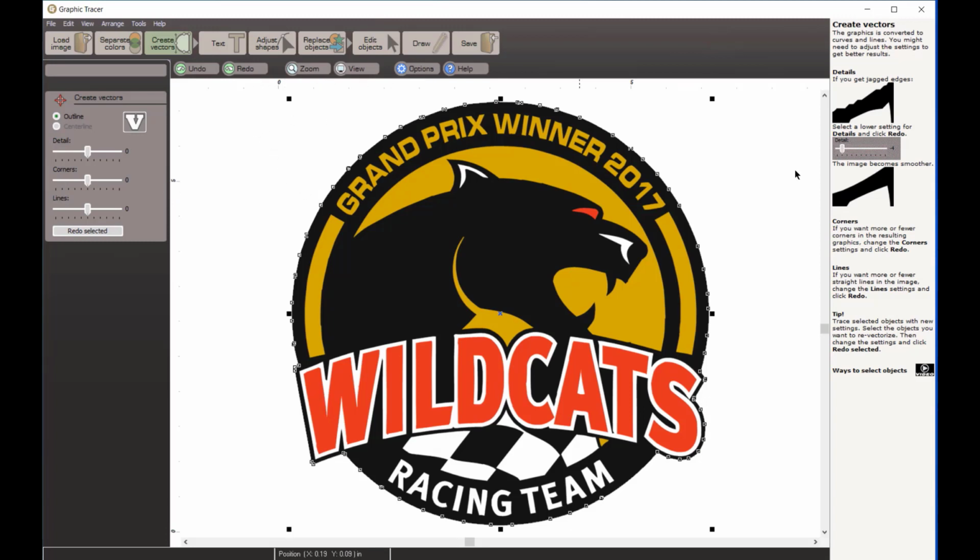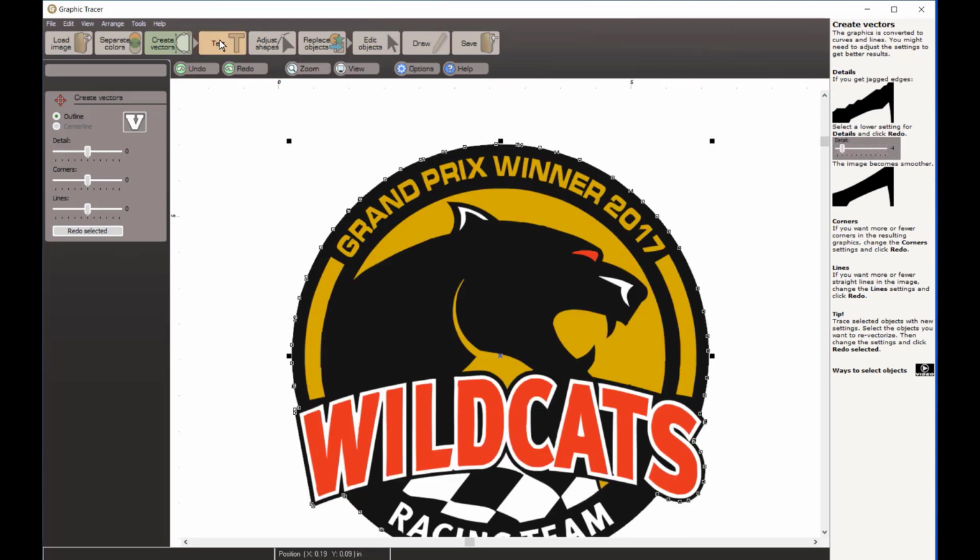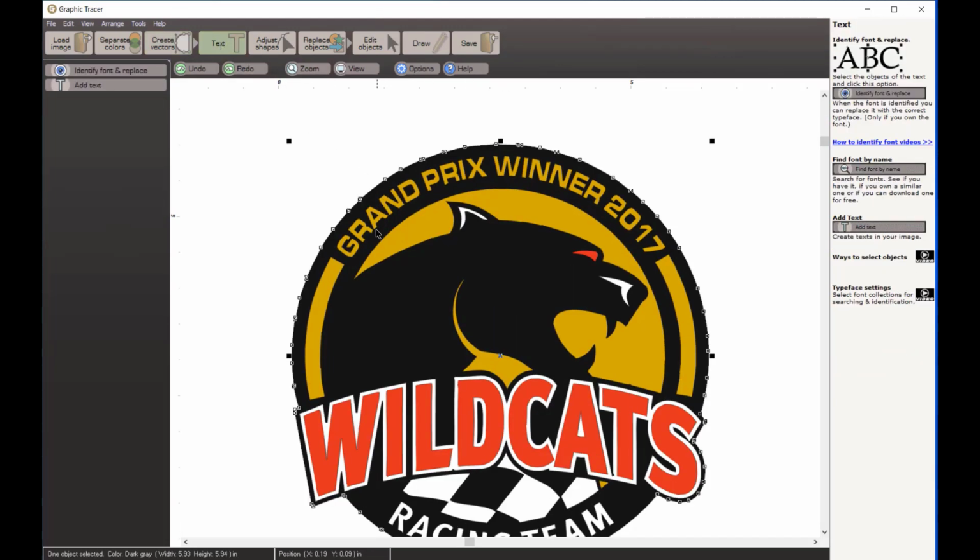So we're going to begin by going to the first cleanup tool over here, our text tool and our FontAI. We have text that's really rough here, and we can let Graphic Tracer, the FontAI tool, do that automatically. So I'm going to come over here and draw a box around the words Grand Prix Winter 2017. And we're going to go to identify font and replace.